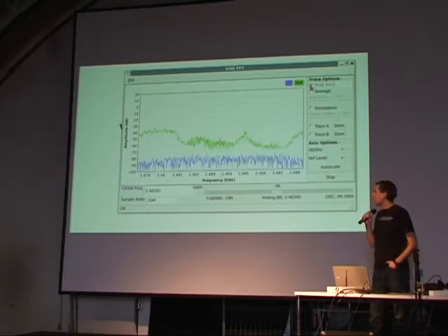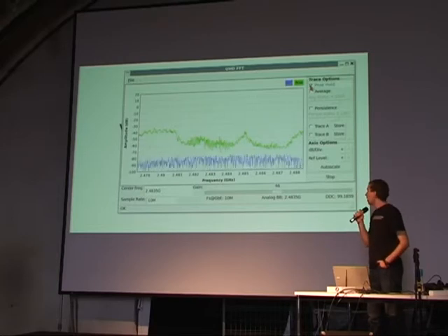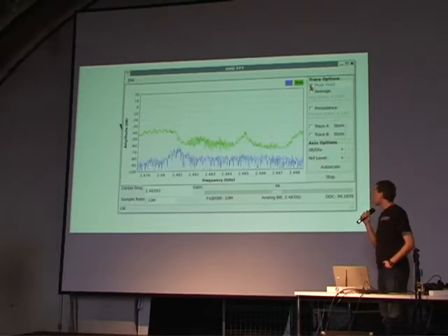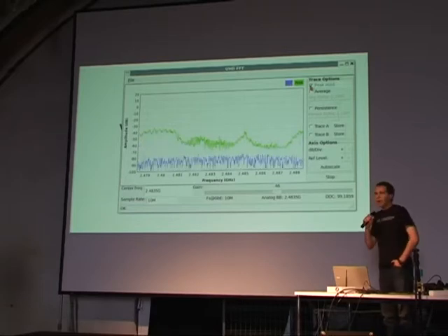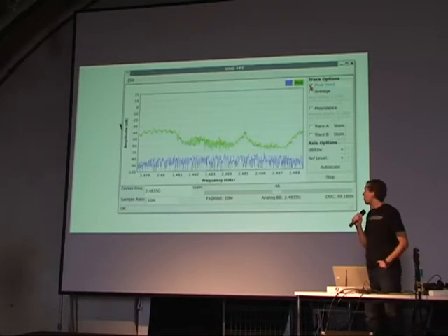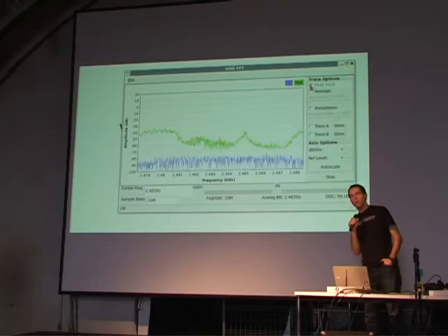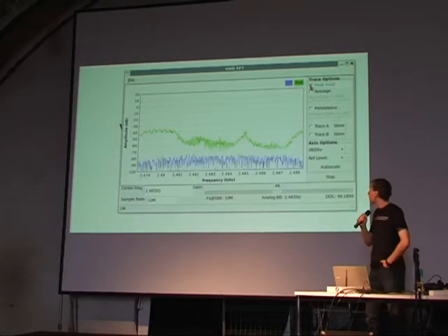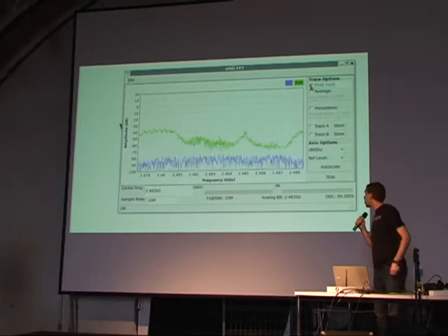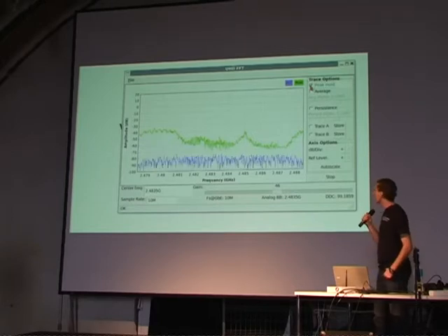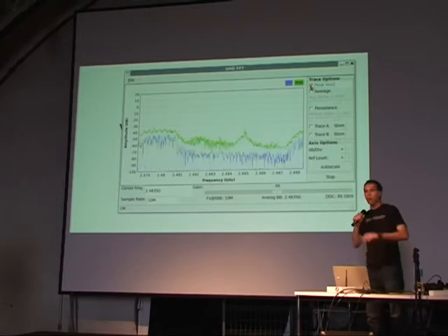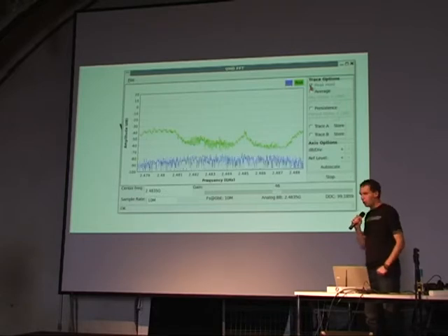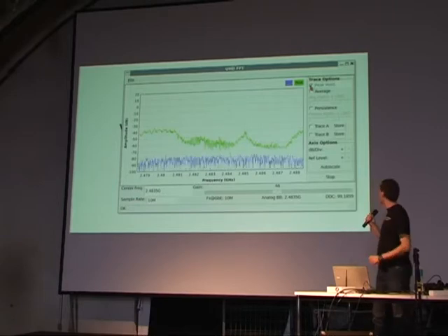What I do is I hold a peak. That means I just take the highest point and lock it in order to realize that there is a pattern that is occurring in a certain set of frequencies. If you do this in a lab and it isn't actually showing too much here, you don't necessarily have that much communication in the wireless as we do have here. So a sufficient demonstration of an FFT just showing one peak for one badge or one set of frequencies is not necessarily possible, because I had to switch out all badges that are here, or that at least are in the receivable area, which I did not do, or which I cannot do. But normally you just get one of these peaks.